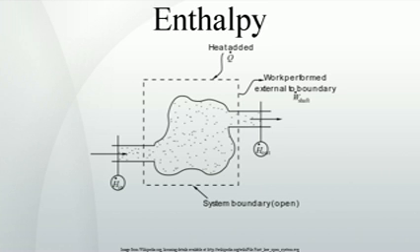The region of space enclosed by open system boundaries is usually called a control volume, and it may or may not correspond to physical walls. If we choose the shape of the control volume such that all flow in or out occurs perpendicular to its surface, then the flow of matter into the system performs work as if it were a piston of fluid pushing mass into the system, and the system performs work on the flow of matter out as if it were driving a piston of fluid.